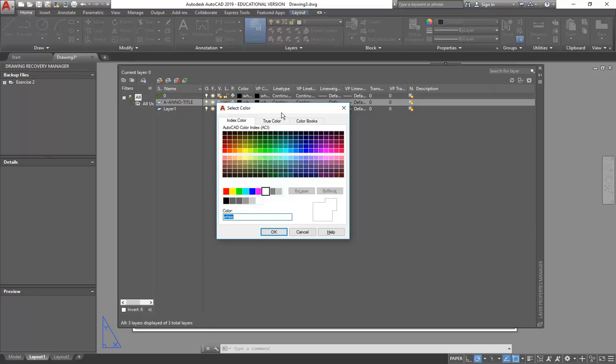If you look at a massive drawing with everything white, you can't tell which layers things are on and what the materials are. So I tend to use the materials as a guide for the colour I want. If it's, say, masonry, the standard colour for masonry is like a terracotta, so I use one of these colours that are like that, around colour 30 or so. You can use whatever colours you want. AutoCAD used to be limited, but now you can choose any colour.